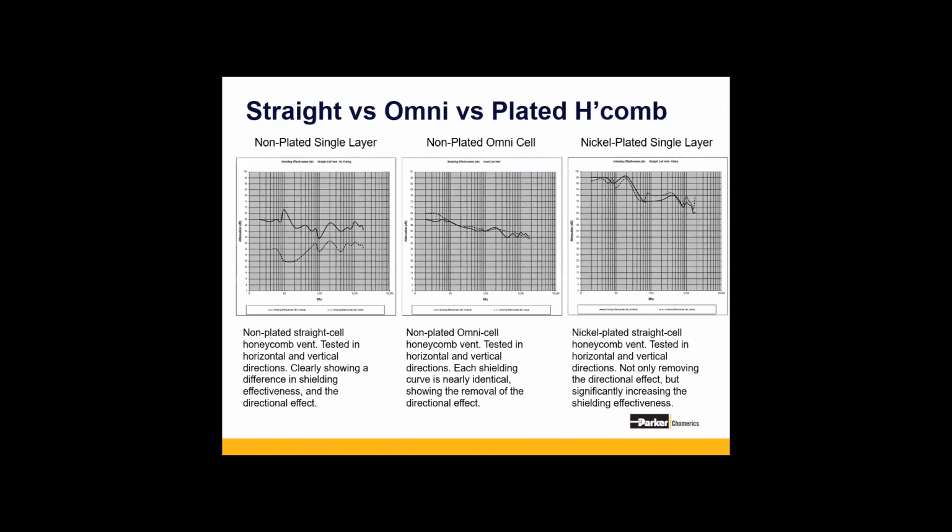And finally, on the right, the nickel plated honeycomb, because that nickel plating is covering up those non-conductive nodes, you're both removing that directionality, but the nickel has that better shielding effectiveness in the range of 80 to 100 decibel.